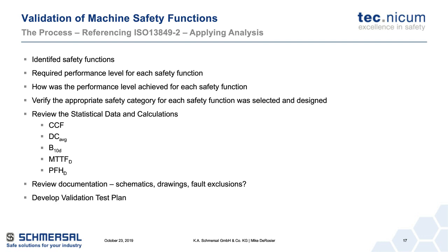Next thing you see on that list is the statistical data. What's the reliability factors? What's my diagnostic coverage? I may not have gotten that far yet. So your analysis portion of the validation pauses right there till you get to that point. However, you don't want to wait until you've actually ordered all the components, wired it all up, got it into the system, and then start doing the calculations, because you may find that based off of the usage, maybe the circuitry is okay, but that particular switch that's in the circuitry cannot handle the life cycles that you're trying to accommodate for that safety function. So as a result, we may have to put a different switch in that circuit.